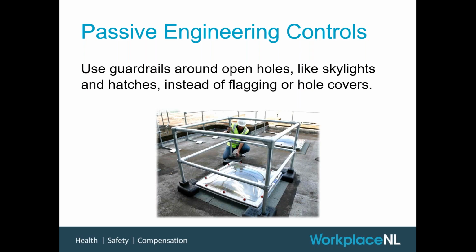This piece of plywood didn't have a label on it, and it wasn't secured. And that's really the rule of thumb with hole covers. You have to have a label on them that says hole cover or open hole or something along those lines. And they also actually need to be physically attached to whatever they're covering up. They can't be easily picked up and moved.